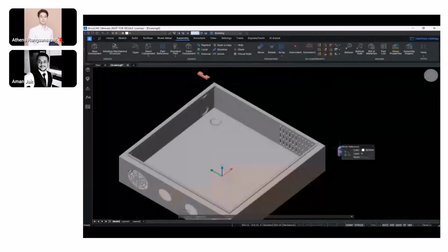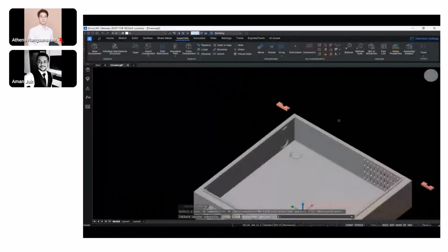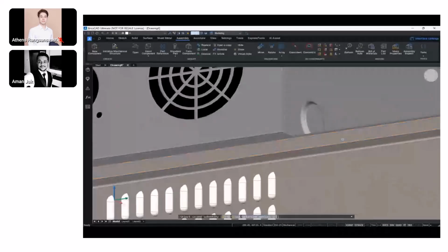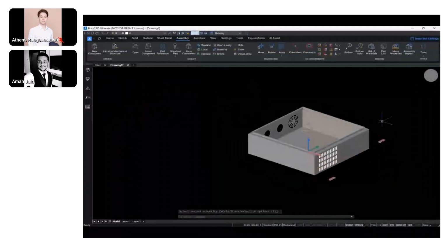Any change in the hinge 2 that we had in the door would be reflected in the sub-assembly as well as the main assembly. Okay, so it's cascading down, right? Let's say if there's a change in the child file, all the parent files would accommodate those changes to those parts as well. Okay, so here's where we are applying constraints to these hinges.